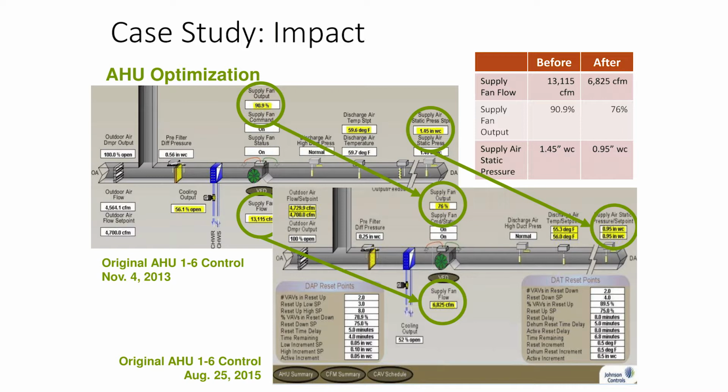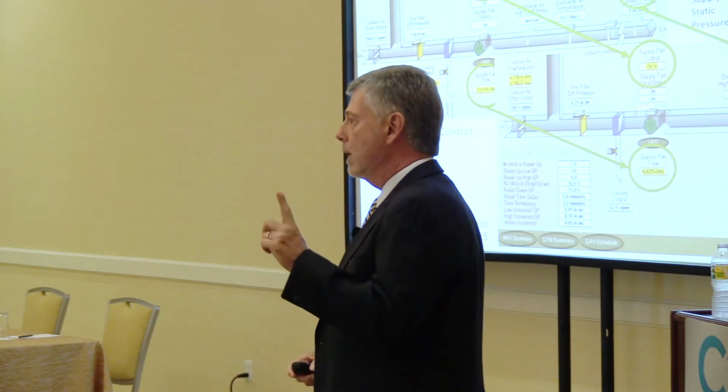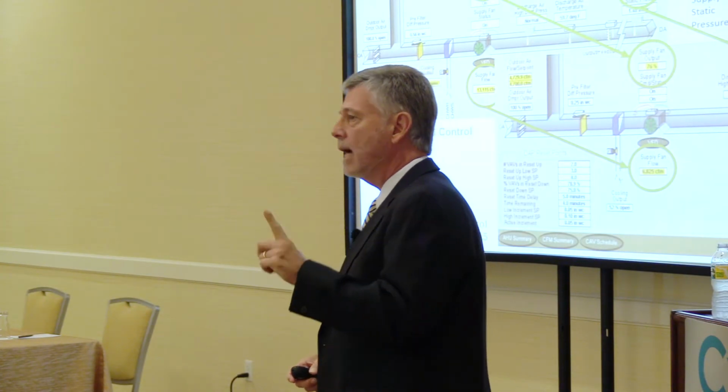We went from 13,000 CFM to 6,800 CFM. We went from 90% to 76% on the VFD output, and we reduced the static from a 1.4 to just under an inch. And we improved comfort throughout the hospital. This was one air handler out of 25 air handlers.